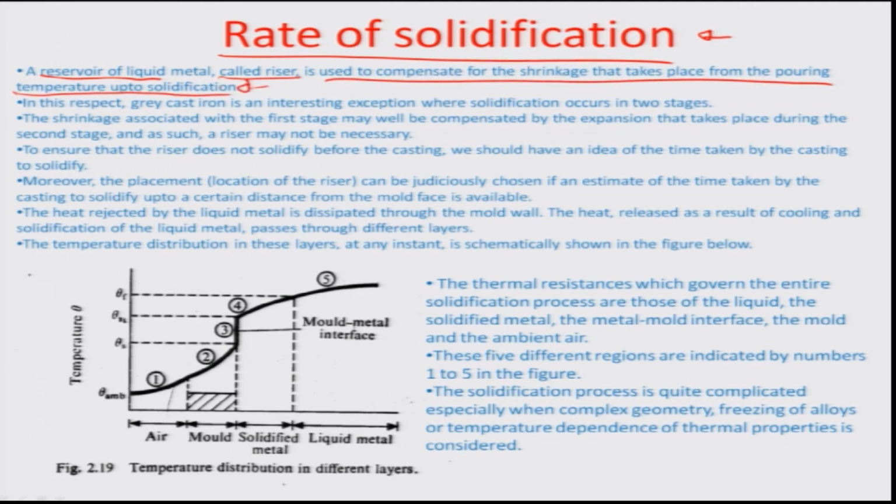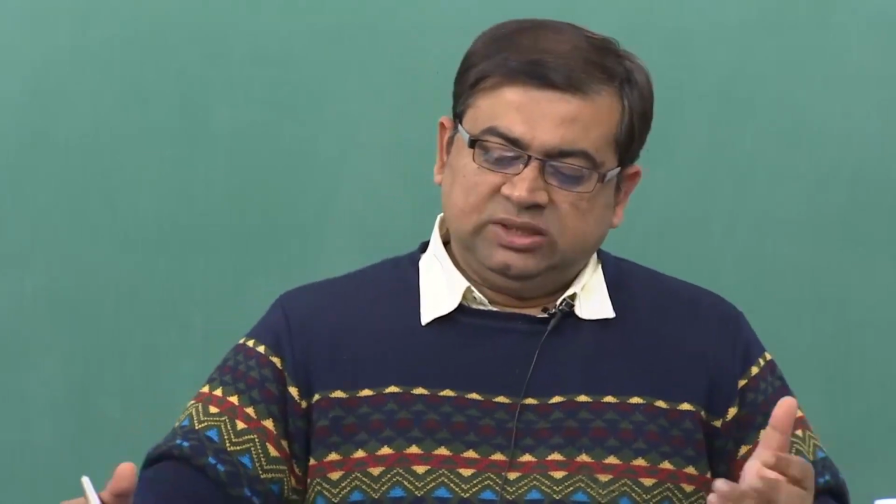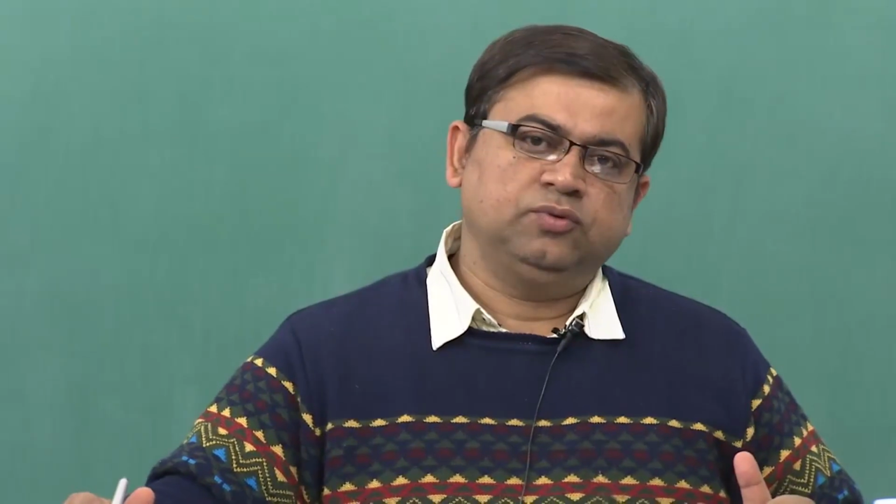I think we had illustrated very clearly that as the liquid metal is poured inside the mold, there is going to be a change in the volume of the liquid metal per se. There is going to be a change because the liquid metal solidifies. So, there is some change of state from liquid to solid, and then obviously the solid contracts, because the temperature comes from the freezing temperature all the way to the room temperature. So, in order to do this compensation for this shrinkage, there is always a reverse flow which is generated, because riser on one hand is an indicator whether the mold has been filled, and on another hand is basically a reverse flow generator which would create no shrinkages, or which would reduce the shrinkages by a backflow of the material from the riser into the mold.